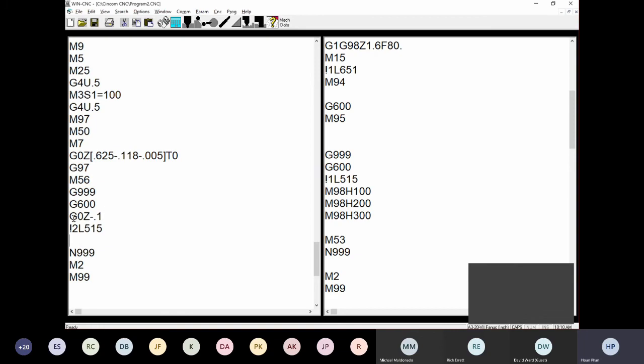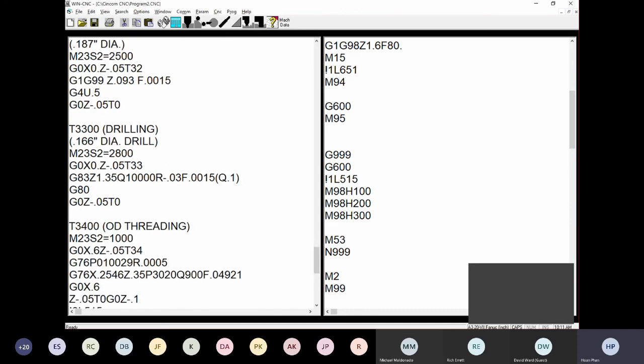If you push back the material on the main spindle, and then you don't put it back again for the start position, the machine will alarm when you run the last part programming. It says basically the start position and end position don't match. So one thing I will do right here is G50. I will put whatever number they had before.